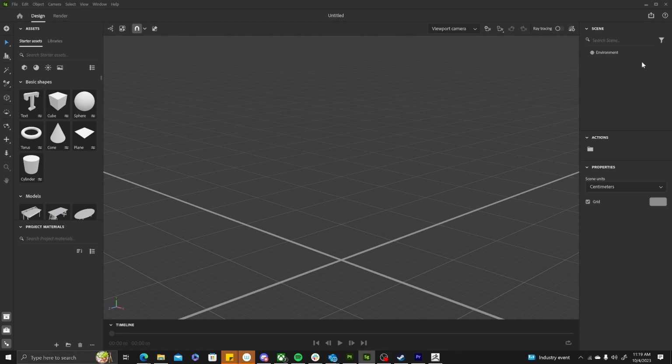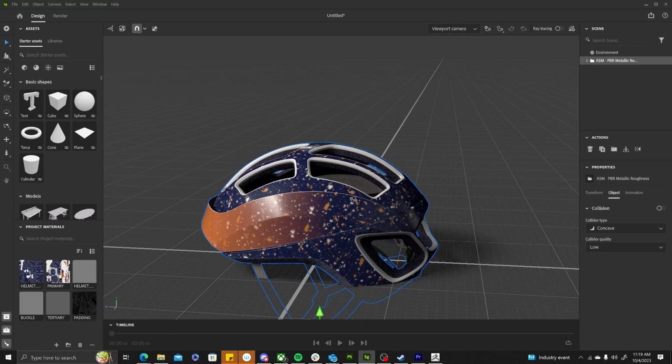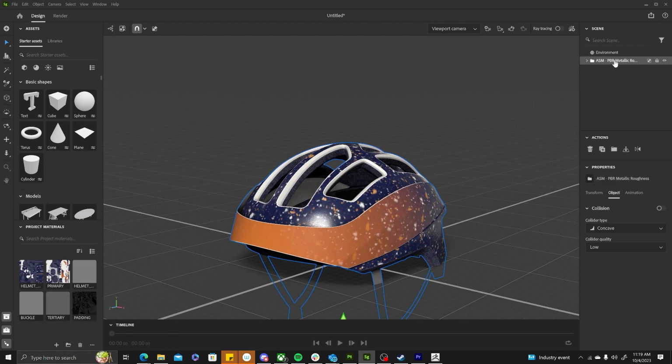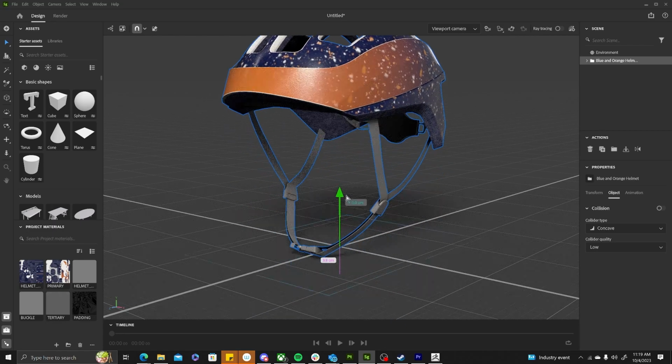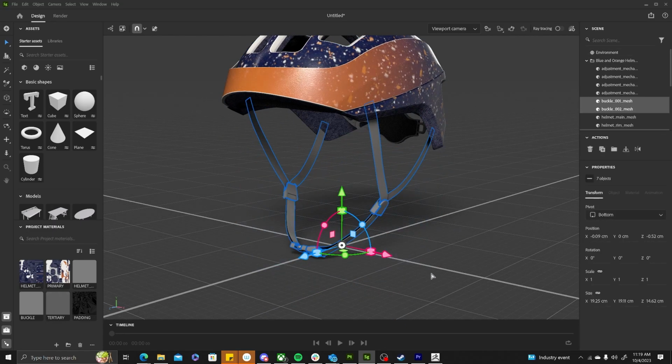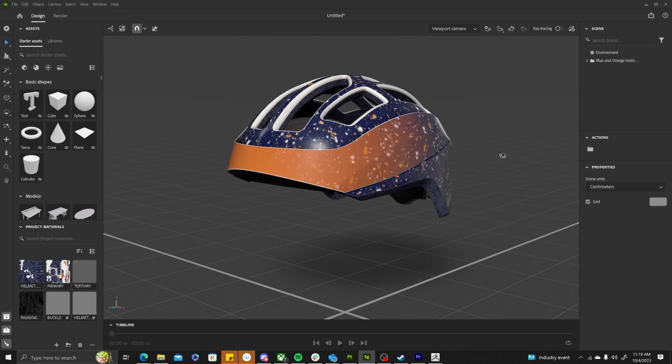So what we can do here, if we needed some beautiful renders, we can just send out a colorway with send to Stager, go back into Painter, make some adjustments, and when we click send to Stager again, it will make a new folder here in Stager itself for that second model, because it's going to consider each colorway two different models. And we can go ahead and rinse and repeat to get all the colors that we're looking for out of Painter and into Stager for a nice quick render.